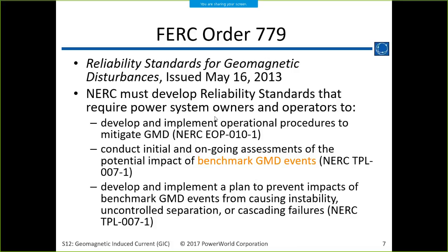In 2013, they issued this reliability standard, and they also directed NERC to put some procedures in place. And of course, they usually end up impacting the operations side kind of first, and then the planning side comes in with requirements for study. The NERC TPL 007-1 came out of that, and it mandated the need to study a benchmark GMD event, which we'll talk about a little bit later, and putting plans in place to look at those impacts.